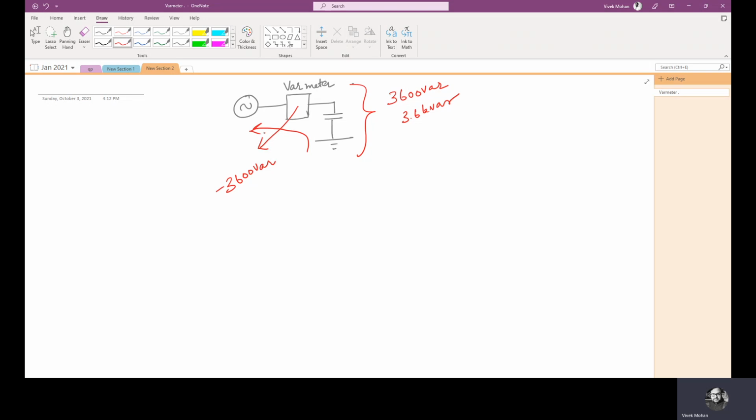Before this, we considered a circuit in which we had a pure reactance with capacitance. Then we removed the reactance. At the time when both the capacitance and reactance were there, the capacitance was delivering reactive power to the reactance, and the generator was not delivering any reactive power in that particular example, because we considered 4 ohms capacitive reactance and 4 ohms inductive reactance.